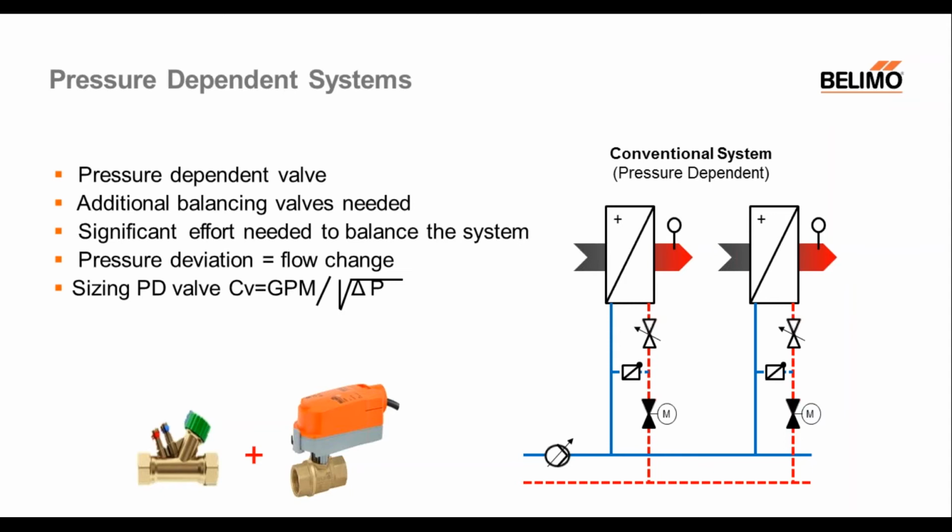So I use this chart to depict that a pressure dependent system, although there is a manual balancing valve installed, you are not dynamically balanced. You're balanced at commissioning, and when the balancer walks the job and he balances every loop, at full load you're balanced. But once the system is in operation and you're operating at part load, or not all units installed are being operated, your balancing job that was done previously has been negated for the fact that there is diversity in the system now.